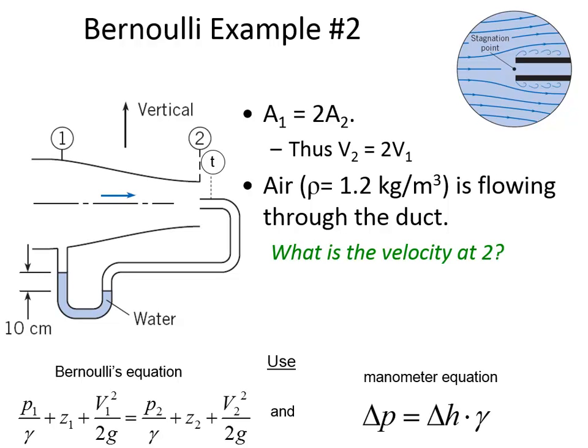This tube is a stagnation tube. There is no air movement inside of the tube. The wind is going along and then it just sort of dead ends. It stops. The wind doesn't continue blowing through the tube. It would shoot all of the water out of there. And so conditions are static inside of the tube. That means that inside the tube there's no velocity.